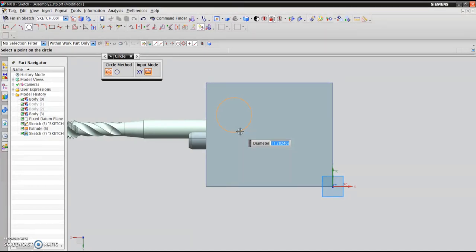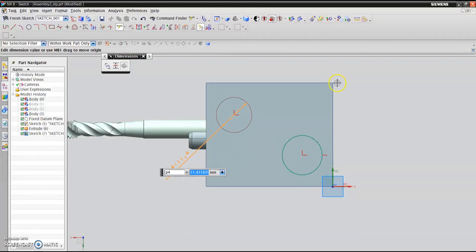As we did in a cross section cut, we select the distance from one pitch to the next. That's the pitch distance. Now, the thread height is the difference between the major diameter and the minor diameter. So the height of the thread is the difference between those two radially. Okay, let's go back and create the diameter that we need.